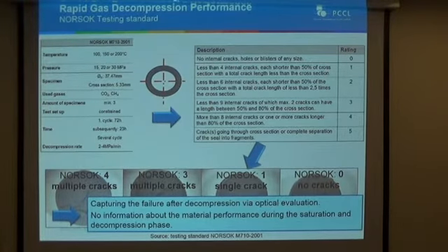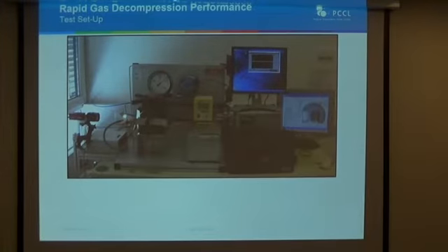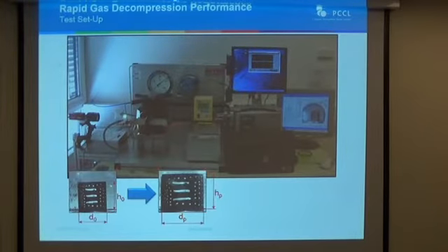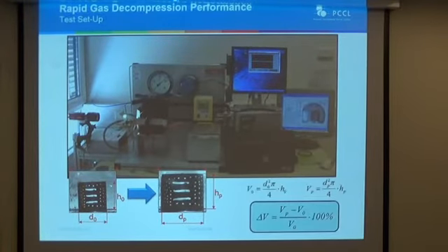And therefore, our scientific contribution was to equip an autoclave test system with a camera system to see directly what's happening during the compression and during the depressurization. Due to the equipment with the window here and the camera, we can see the volume increase inline and can then, based on the cylindrical geometry of the specimen, calculate the volume increase.